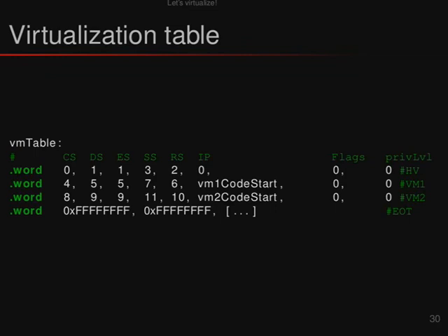And I need to save that, because if you do the compare, and afterwards you would branch, but then the context is saved, and another context is loaded and executed, the flags register most likely will have different values after the restore of the first context, which executed the compare, and then it will branch into the wrong direction. So I need to save this flags register also. And the last field, the privilege level, is still unused.